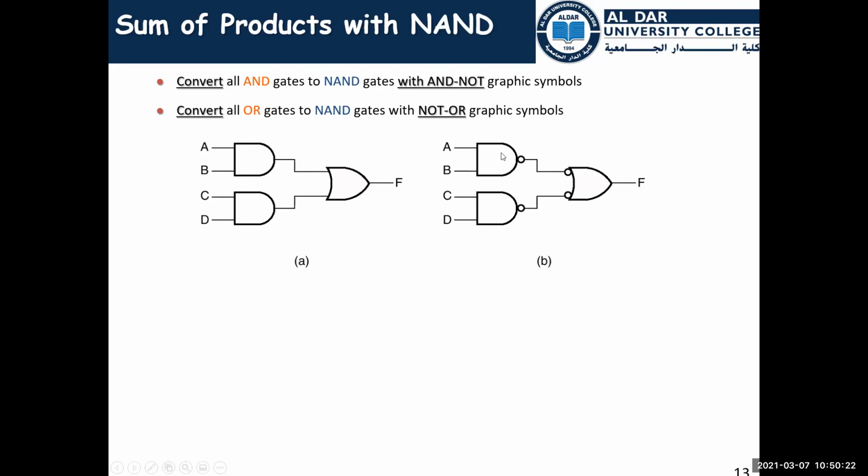Then we have here, okay, that's good. We have a NAND gate here, we have a NAND gate here. What about this one? This one is exactly a NAND gate, because we can draw it here to make you understand. Just make it simple. We have a NAND gate with X and Y, and the inputs are 0,0, 0,1, 1,0, and 1,1. The outputs are 1, 1, 1, 0. This is the NAND gate.